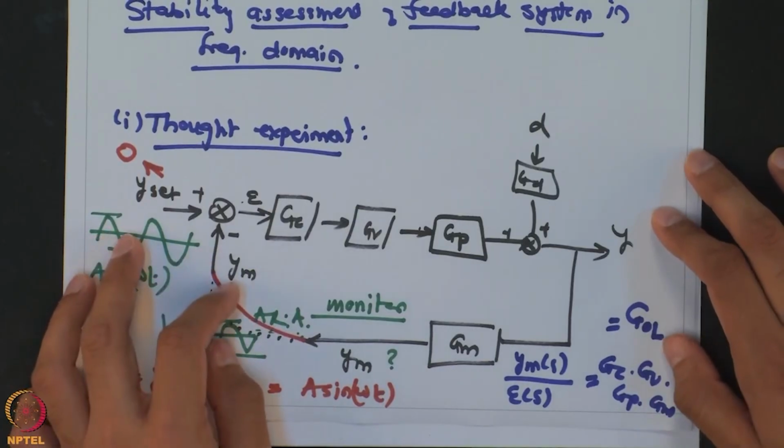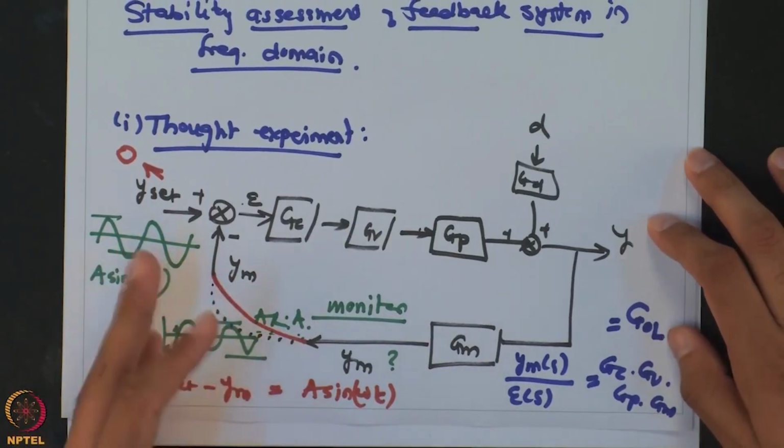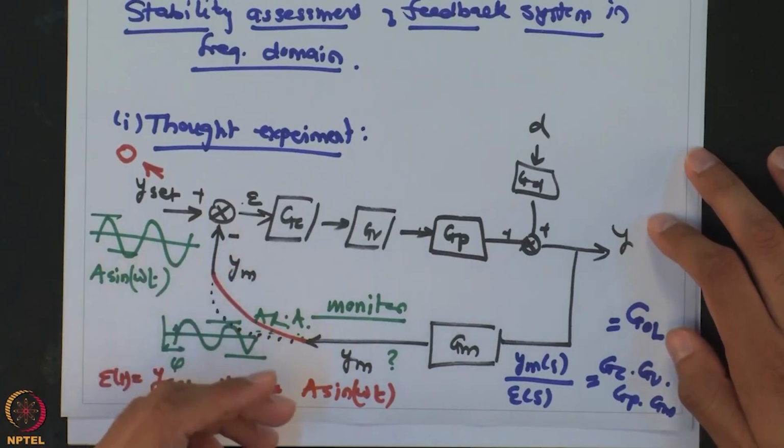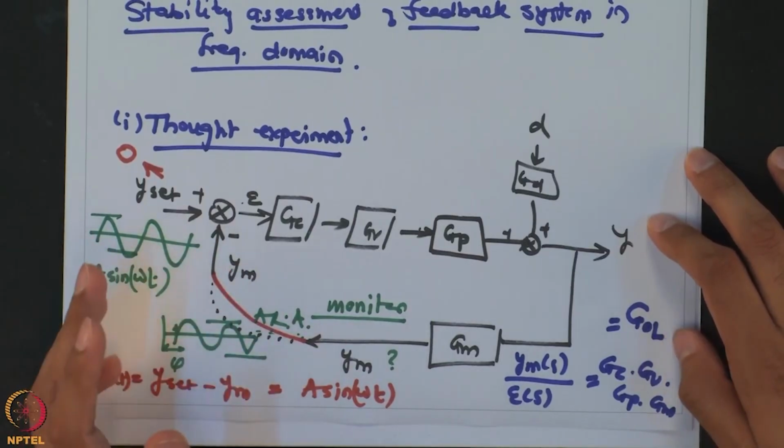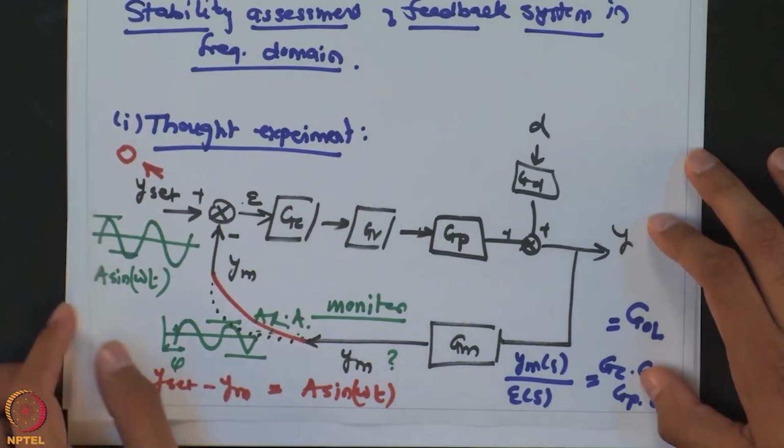So, this Nyquist plot then looks at all these successive periodic values of frequency when these phases are multiples of 2n plus 1 pi, and then takes that into consideration. If AR particularly is not a monotonous function of omega, then just satisfying this condition at minus pi is not sufficient. You have to look at the condition at every successive 2n plus 1 pi and ensure that all those ARs are also less than 1.